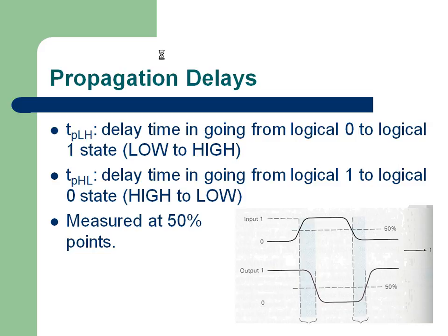and let's say this capacitance is 10 picofarad. For the 10 picofarad to reach 1.8 volts VDD with 1 milliampere of drive, it takes, let's say, T1 amount of time. Instead of 1 milliampere, if you have 10 milliamperes of drive, it will take much smaller time. Maybe you can approximate it to be 0.1 times T1 to reach the same 1.8 volts.